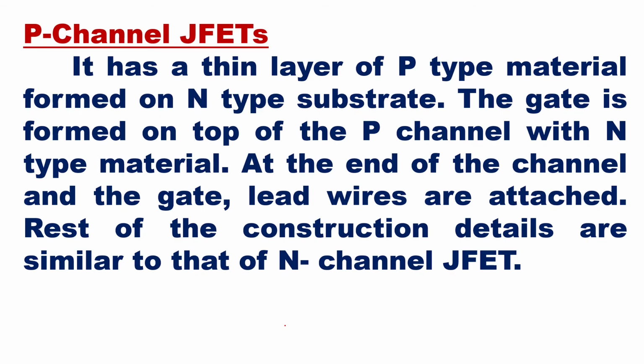Only thing here, the bar will be of p-type semiconductor and the gate-induced small parts of semiconductors will be your n-type semiconductor. And if you go to see n-channel JFET, your bar will be n-channel, and the point where you have to have the gate terminal, there you will be having p-type semiconductor. It is only the semiconductor material that is going to differ, whereas the logic remains the same.